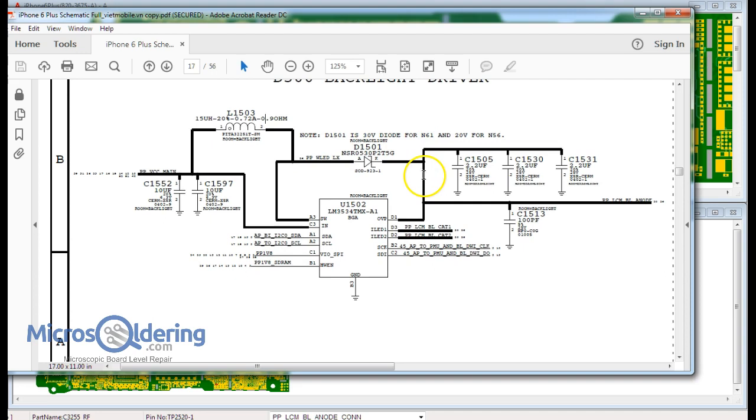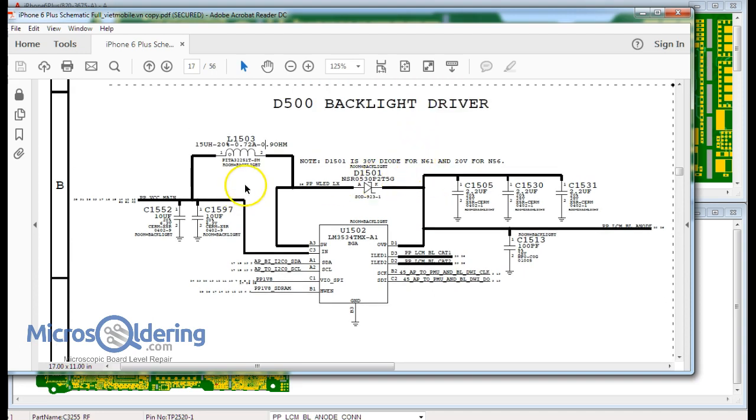Okay, so since the 6 Plus has two different circuits, I believe maybe the coil is a little different in the other circuit, which is why the voltages are different. Anyways, let me see if I want to go through this whole thing or not. Alright, so VCC main comes in at roughly 4 volts. The inductor boosts it to about either 11 volts or 17 volts, depending on the rating of the inductor.